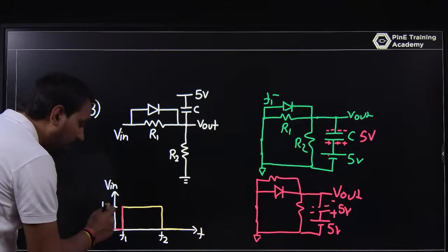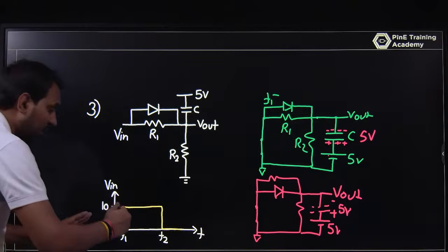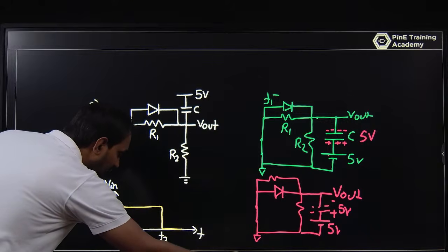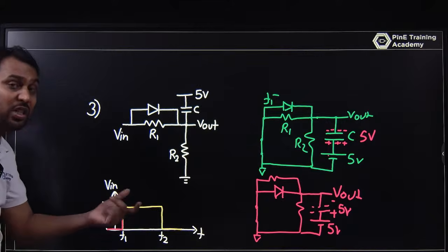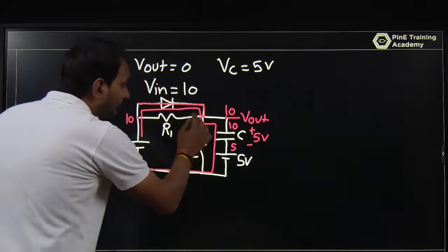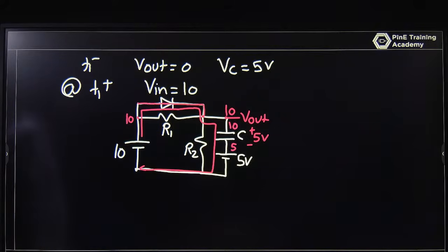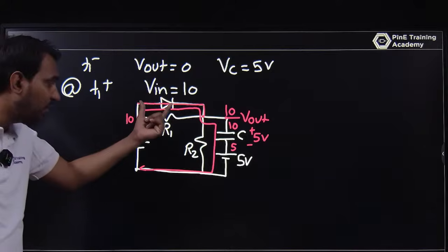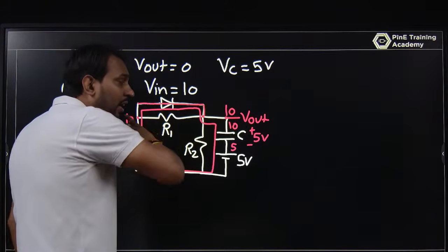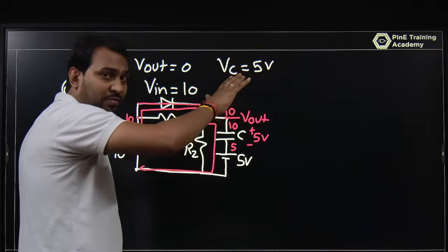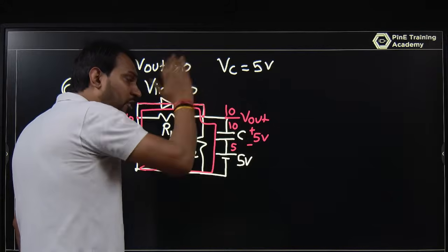So that is the power of the diode. The diode just makes that short. It is not like charging like this. It is not taking time, because tau is 0, because there is no path with any resistance. So that is the beauty of this question. With the help of the diode, the capacitor will charge fast. It will not take time, but it will take time to discharge.